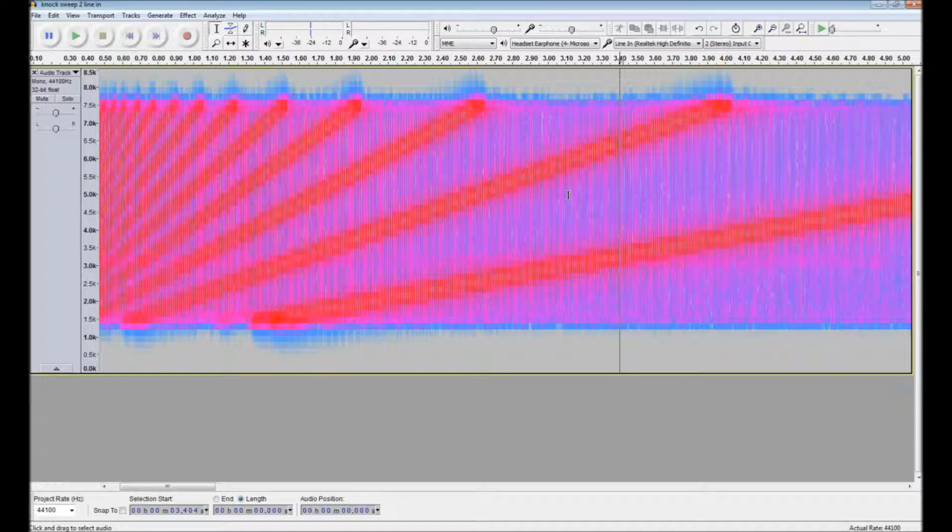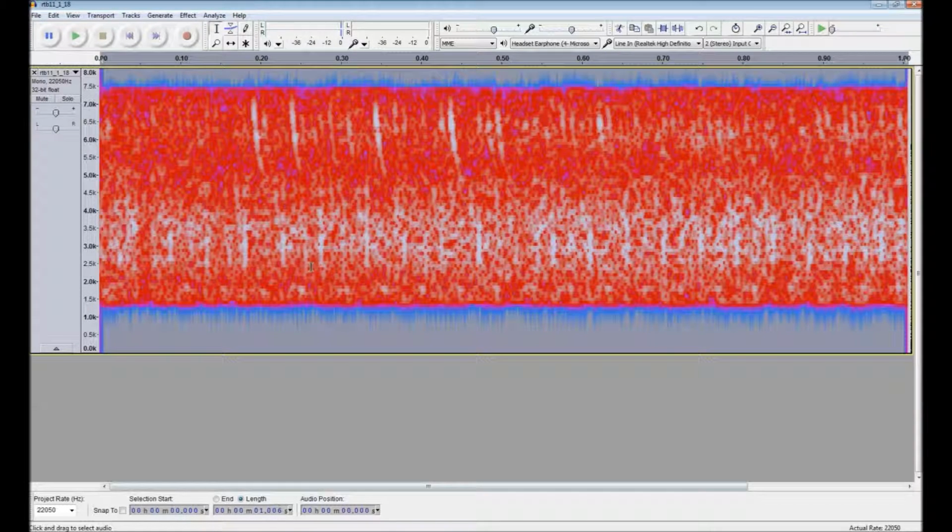If we instead had filtering from 4K up to 8K, we would never have phantom knock ever, and that's the God's honest truth. If you can see it for yourself, from 5K down to 0, there is a ton of crap on a properly running engine, and that's what causes phantom knock.